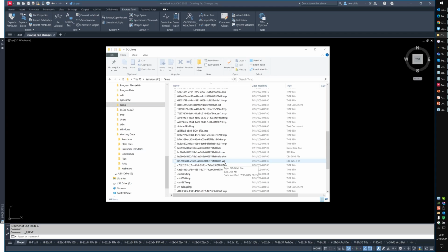And there's actually a whole process of things that occur. One of the other common things is that if the save is impacted by something like file replication, if you're trying to save up on an appliance like Nasuni, things like that, where the temp file that gets saved over is not renamed to the DWG, you end up with something that looks like this. That's a .tmp. This is actually your drawing in the drawing folder. But these are the things you've got to be careful of.